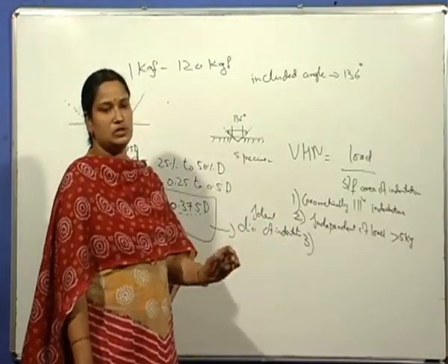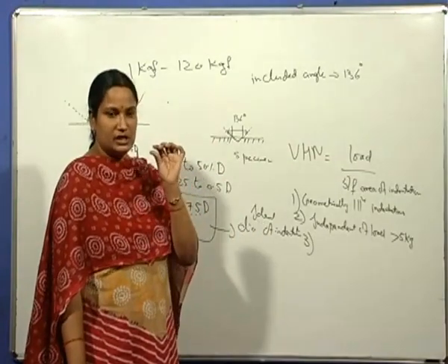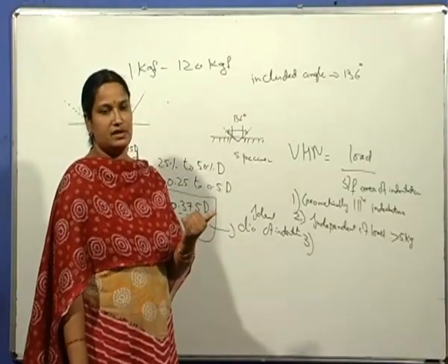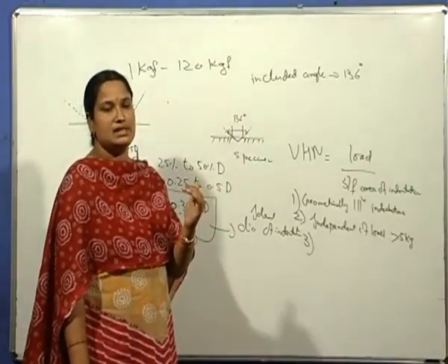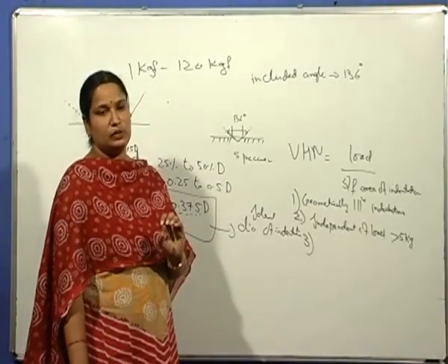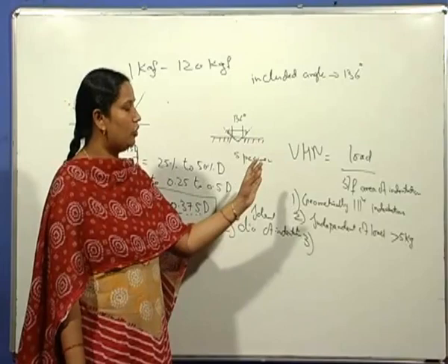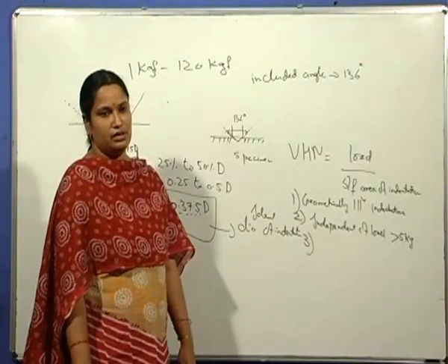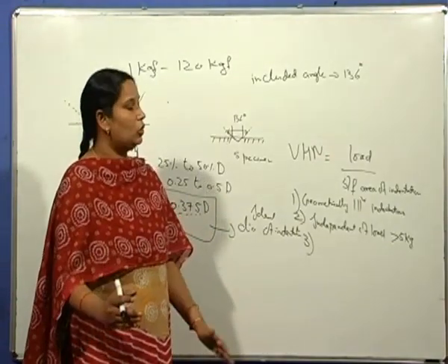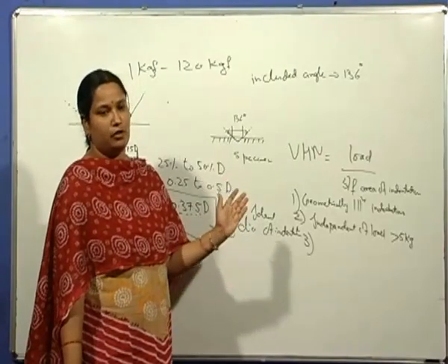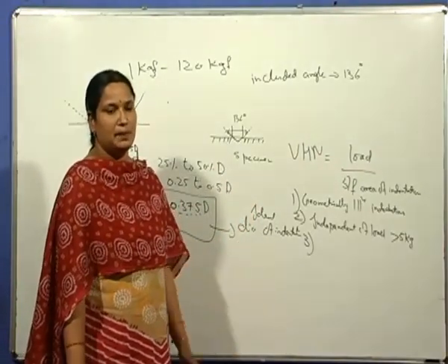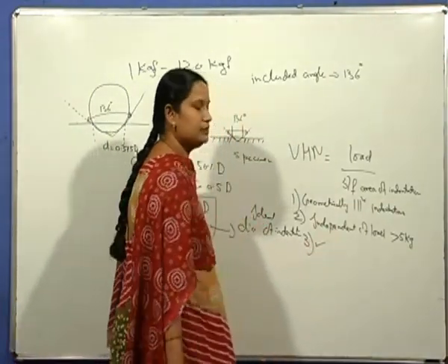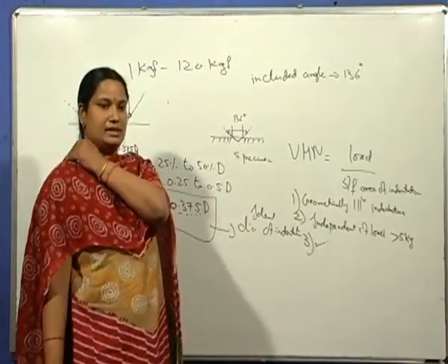Even this method can be used to test very thin materials, very thin specimens, as well as the coatings given, or the hardened coatings like the carburized layers, as well as the coatings given to the materials. So one can determine the hardness of all these things by using this Vickers hardness without the need to change the indenter. So it provides a long range scale over which almost all the hardness of all the metals and alloys can be determined by using Vickers hardness test. So this is one more advantage when compared to Brinell hardness test.